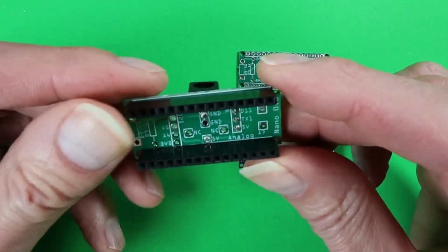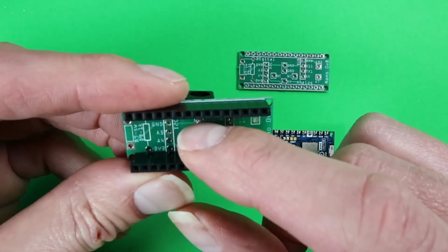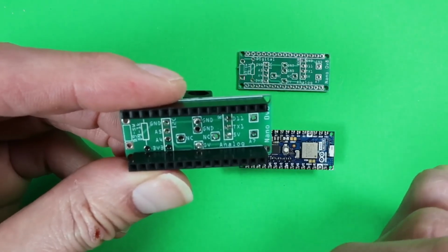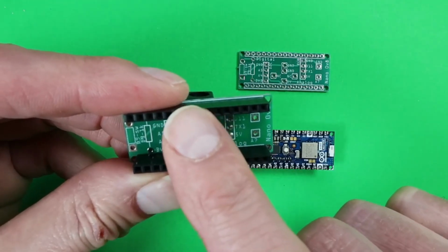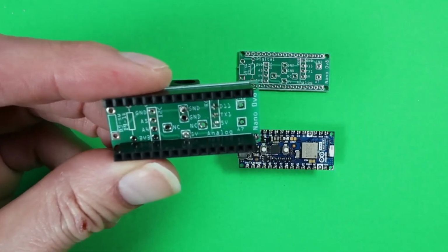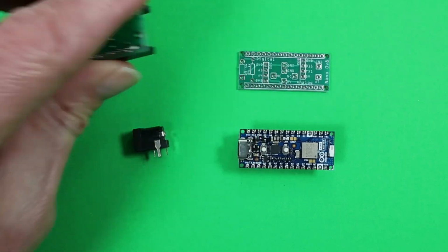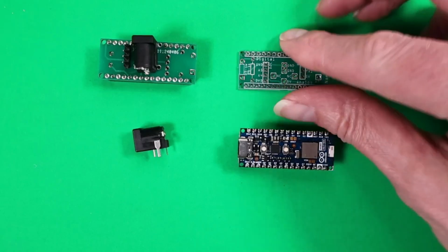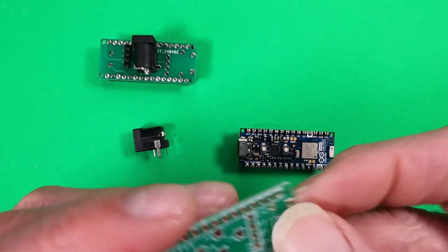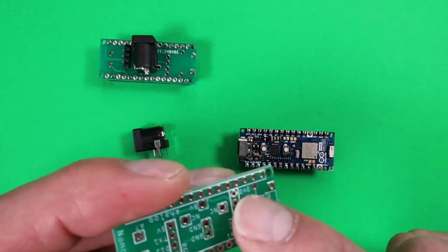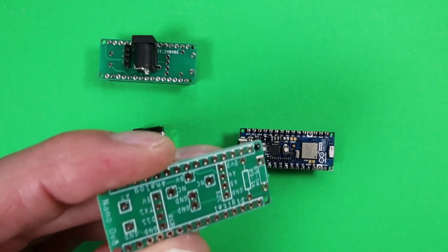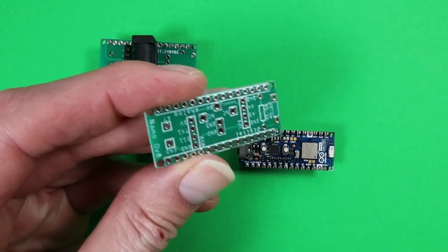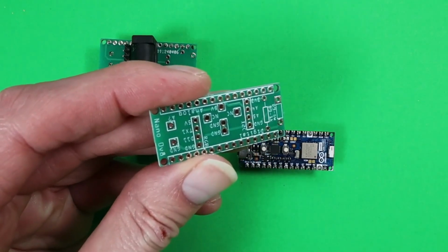But they can alternatively be mounted on the top of the board to allow it to sit flat, though you will need to not fit the center header sockets and pins for the Arduino in order to leave the power socket exposed. For use in other projects, I2C pins are brought out to a second header along with 3.3 volts, or these could just be used as general digital or analog inputs and outputs.